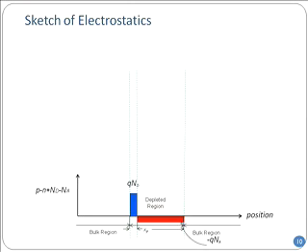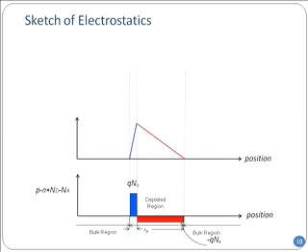If you have the charge, do you know how to calculate the electric field? You know that. Area under this curve up to a given X is the electric field. This is the electric field. Because you have a rectangle for the charge in the bottom, as you start integrating from the left-hand side, every new slice adds a constant amount. So an integration of a constant function becomes a straight line in the electric field plot.